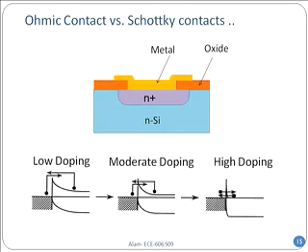So what do people do? If you do not want the metal semiconductor junction to bother you, because that is not the main purpose of your device, let's say you're doing a normal PN junction diode, and then you have to put metal on both sides. Now then two Schottky barrier diodes are sitting on the top and the bottom. You don't want that. You just want the PN junction. In that case, the only recourse you have is to dope the N side very heavily. That's why you see that in the purple region, I have shown N+. N+ means very heavy doping. And what it does is that when you have very heavy doping, then the electrons don't have to go over the barrier. They can just tunnel through the barrier. And as a result, the resistance may be minuscule in that case, because they can just go through the very thin triangular barrier region. Now that's for one type of carrier.